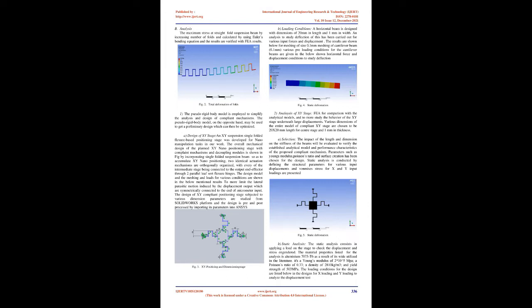16. Large deflection behavior of clamped beams and a folded flexure design is modeled, and a comparison of several suspension designs is presented at low driving voltages. 17. Governing equations to calculate stiffness are derived from Castigliano's theorem, the Rayleigh energy principle and strain energy for serpentine folded beams. 18. A flexure-based differential XY micro-positioning stage driven by piezoelectric actuators was proposed in this study, with finite element analysis and experiments to validate its performance.